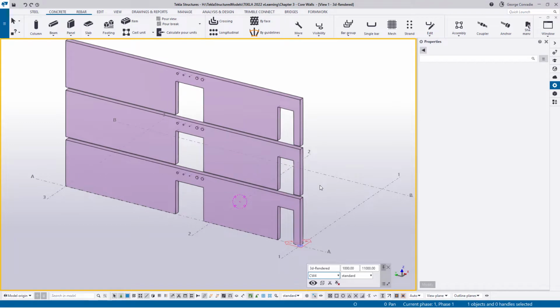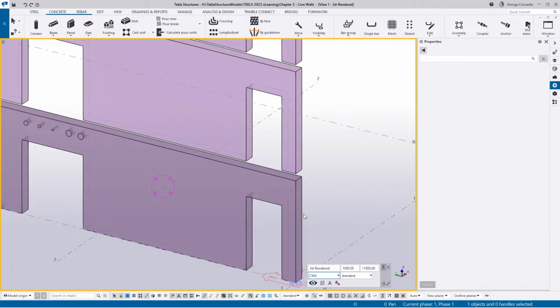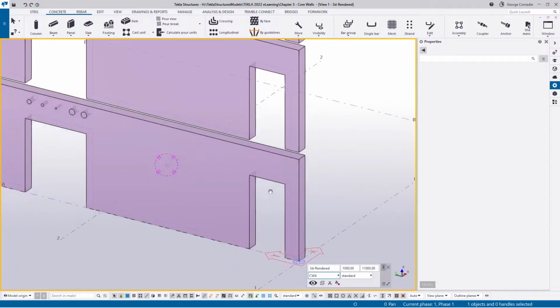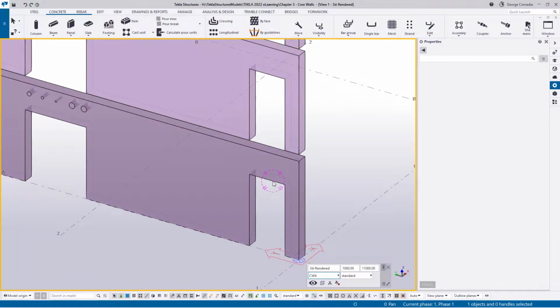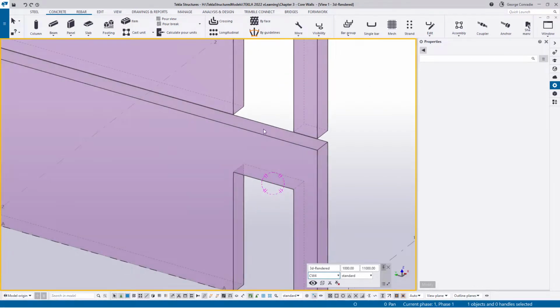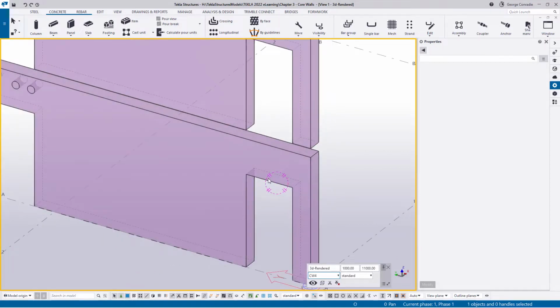I have some reinforcement noted next to me. It's not an actual replication of an actual design. It's just based on some experience. I'm just going to use realistic bar sizes, and over this door the engineer is calling for ligatures of N16 at 300 millimeter spacings, and then he's got 24 millimeter bars, 2 of them in the bottom with another layer on top of that, and 2 in the top with another layer below that.